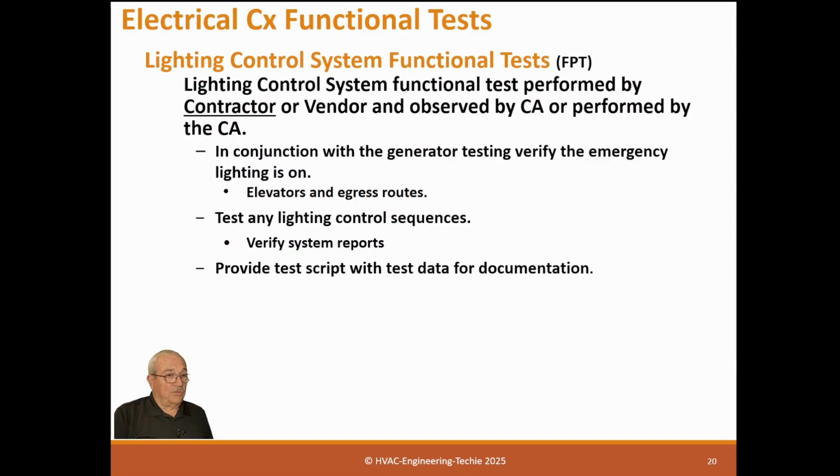So then what you can do is come in an evening, get them all activated, and watch to see what happens on timer. If you're doing it during occupied time, with people moving in and out, it becomes almost impossible to test. So this is one where it's better to make sure the contractor set them all up the same, so you can test them and know what to expect at the same timing.